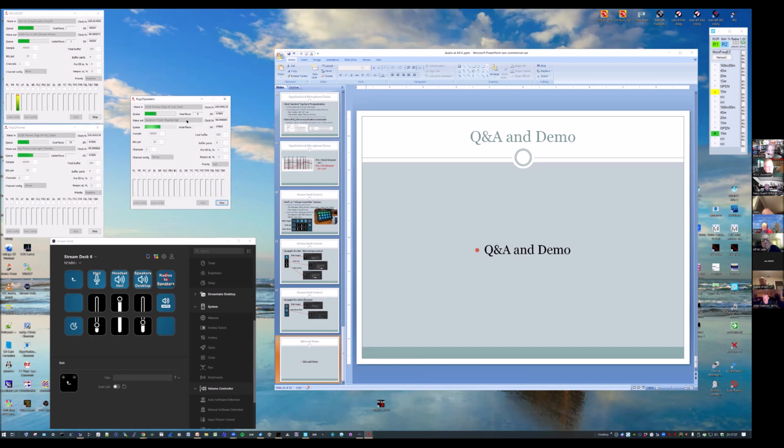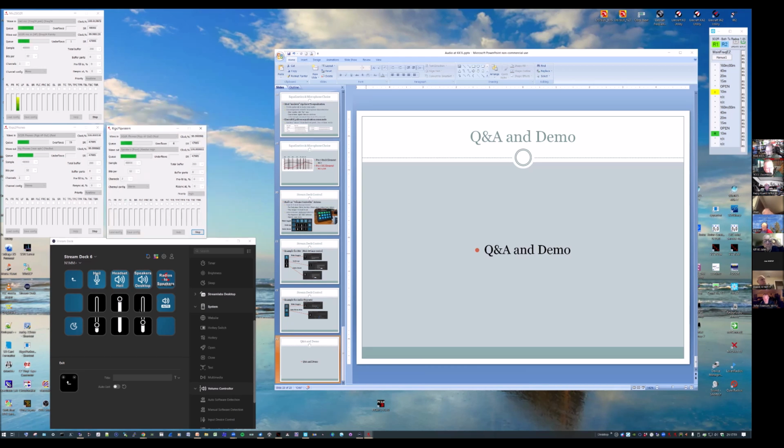So it's a little bit different than a mute. I want to stop the audio flow from my radio to the front speakers. So in order to do that, I have to find out which of the 5 audio repeaters this is. You run auto mode, find out which one of these I can mute, and it's this 4th one that is set up for my radio. Then when I set up this particular button, I would choose the 4th audio repeater device from here to be the one that I actuate. But anyway, that's probably a little bit deep, and I'm sure you didn't follow it.